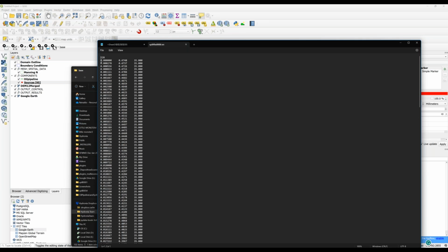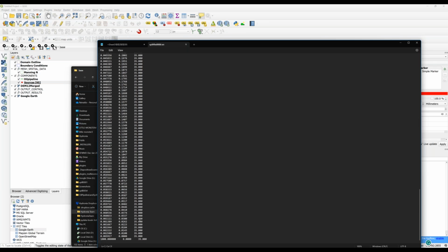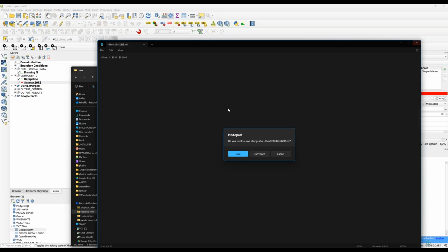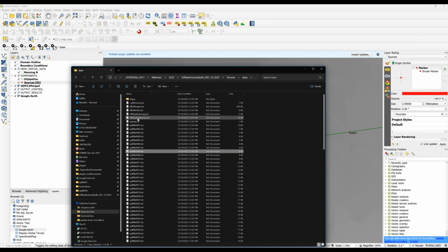You can see here that you have the flow rate, the number of values in the file, the time, the flow rate, and the temperature, because I selected 35 degrees as outflow temperature for the heat transfer model, which is a constant temperature here. So this is the outflow hydrograph from this particular location. And then we have also the energy line.